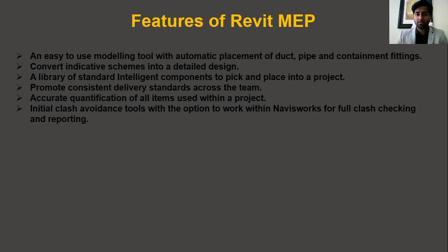While in Navisworks, we have the option to go for more advanced options in coordination, like we can say how much tolerance we should be giving, and all those conditions can be given in Navisworks. So what we can do is that from the model that you create in Revit, we can convert the model into Navisworks, and we can do the clash detection or the coordination over there. And it is easily compatible between the two softwares.